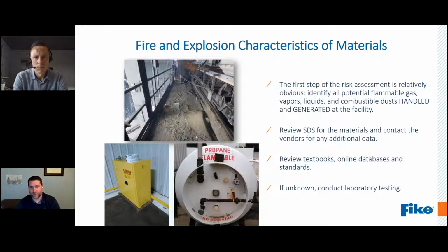However, you do need to make a consideration when you're looking at outside resources, where it's not your dust specifically: the explosibility properties for dust are very dependent upon particle size. You can look at something like sugar, which is a common one. I can see explosion properties that are all over the place, not the same from one to another, and it's all sugar. It's a factor of particle size.